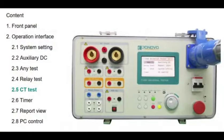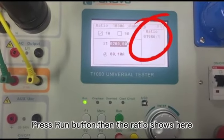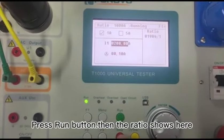The ratio of the secondary output terminal K1 and K2 is 2000 to 1. Connect K1 and K2 to the input ports of ammeter. The rated secondary current is 1 ampere. We set the primary current is 200 amperes. Press Run button. Then the ratio shows here.